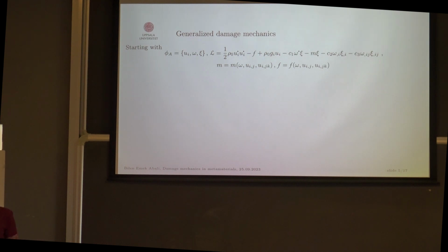Now we start with the damage formulation. In the damage formulation, I have the omega dot, which is the first time derivative of the damage variable, and this auxiliary variable. So this constellation is useful in order to have in the end a balance equation where we have the first time derivative. So that's the main idea of using this auxiliary variable.